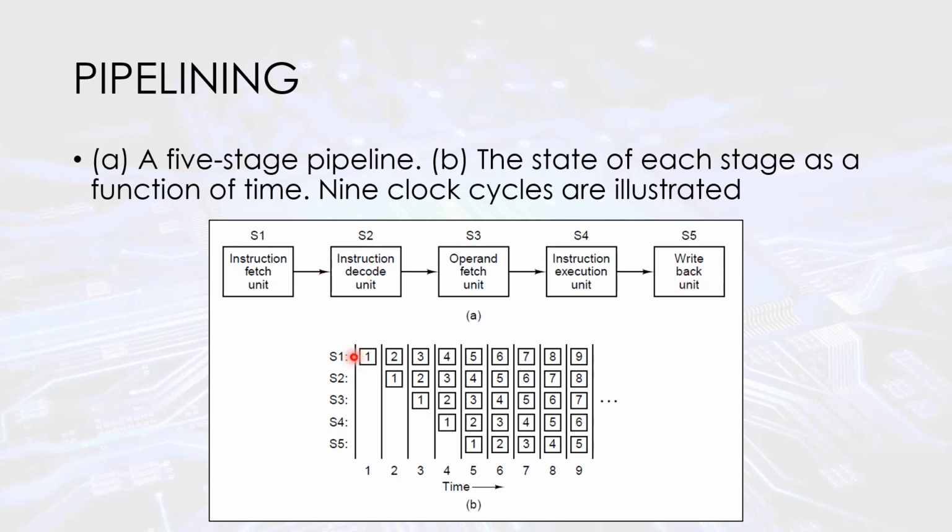Okay, so if you just look at it from a single instruction, it's going to be pretty much the same flow. But the key with pipelining is that by time one, I'm done fetching the instruction for instruction one. I'm done, right? So why just let that instruction fetch hardware go to waste, sitting there doing nothing? So we say, all right, let's start reusing that hardware. Let's go and fetch instruction two.